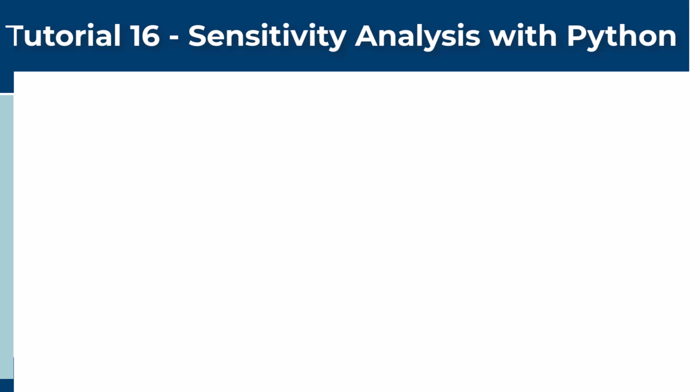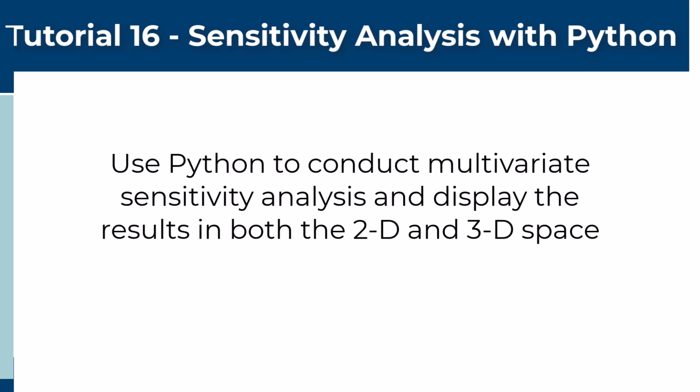The goals of this tutorial are to show users how Python can be used to create a 3D sensitivity map of performance under varied operating conditions. Secondly, we'll see how various plant configurations can be compared within the 2D space using Python to manipulate the scenario being used in GPSX. Please note that the GPSX Pro Plus license is required for Python scripting functionality within GPSX.